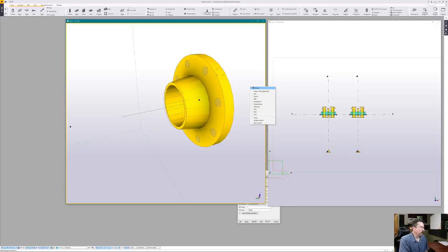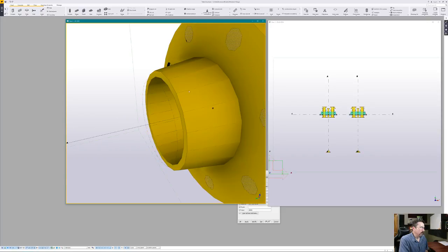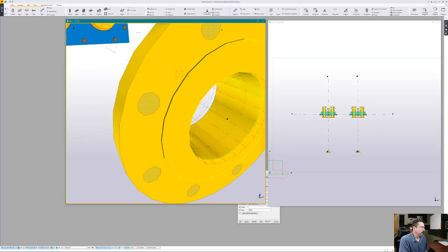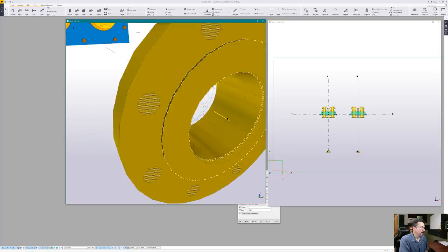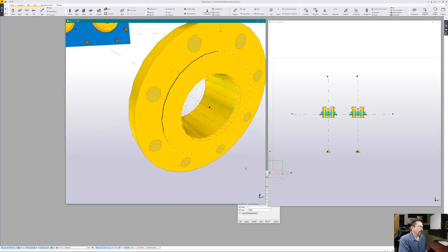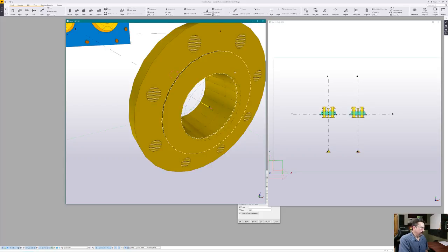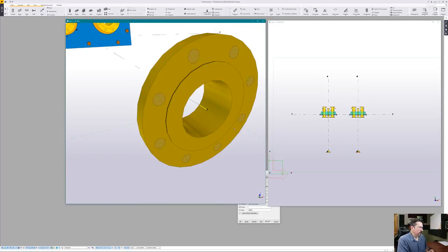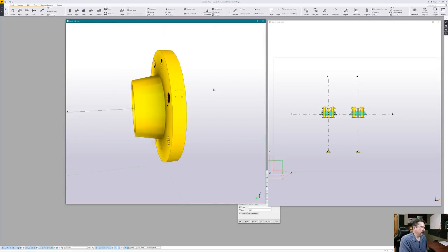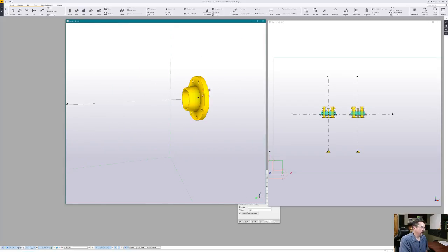You can see all of the pieces in here. We now have these cuts or added material pieces, and there's one that goes around the edge of the raised face there. And if I just redraw, all those go away. But now you can see if I hover over it, the whole thing selects. So it's all one piece now. So with that, we have now created this piece as being its own.